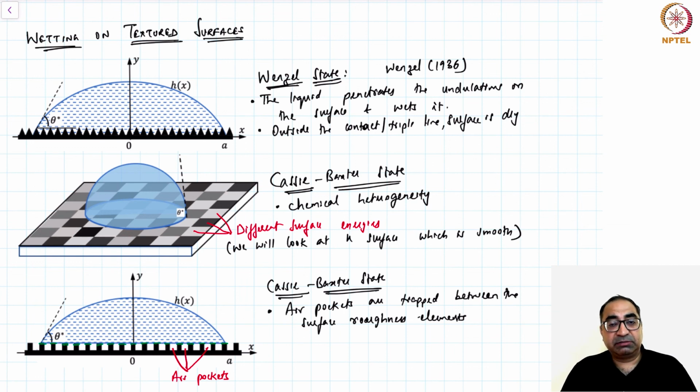So the roughness parameters one can play around with, with careful engineering, to get roughness elements the way they want. And then the next step would be to do some chemical treatment to change the contact angle theta Y. And then one can try and make surfaces with specific properties. So with this, I will end the discussion on wetting on textured and rough surfaces.